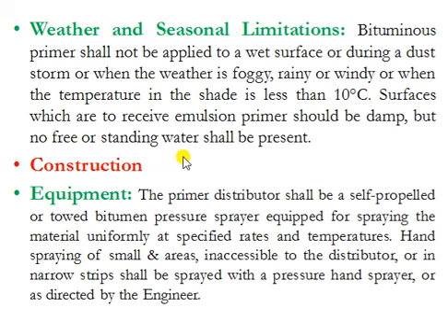So the ideal condition for spraying of primer is that the surface should be damp, but it should be free of any standing water. So it is the ideal condition for spraying of a primer. So next is construction. So how it is constructed.